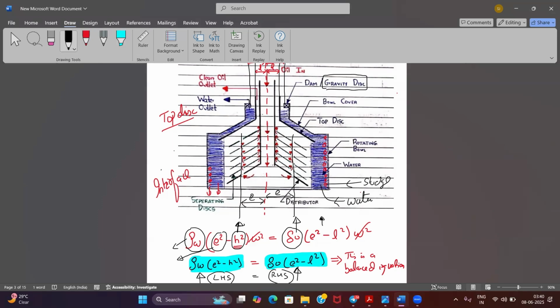Now, suppose a supplier has given you oil in which the density of oil is higher. For example, the last bunker that you had, you were using a density of oil as 0.9. 0.9 was the density of oil that you were using, HFO. Now you get a new bunker in which the density of oil has increased to 0.98. So what are you going to do in the purifier?